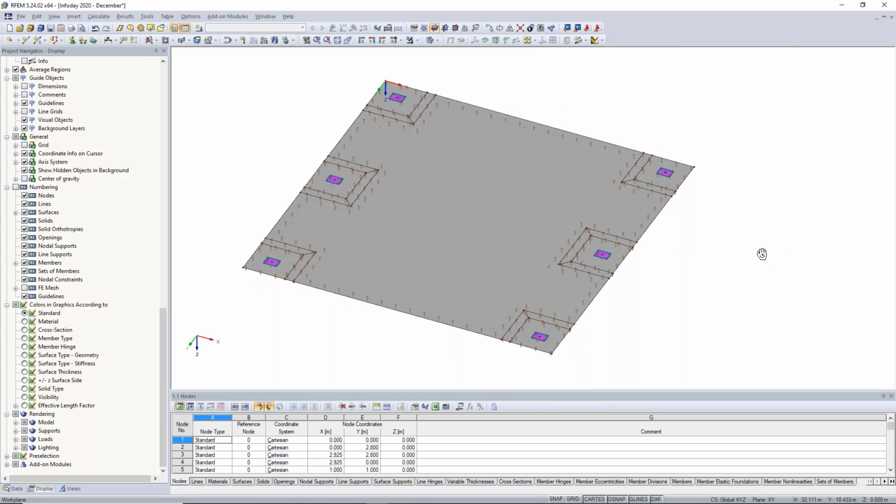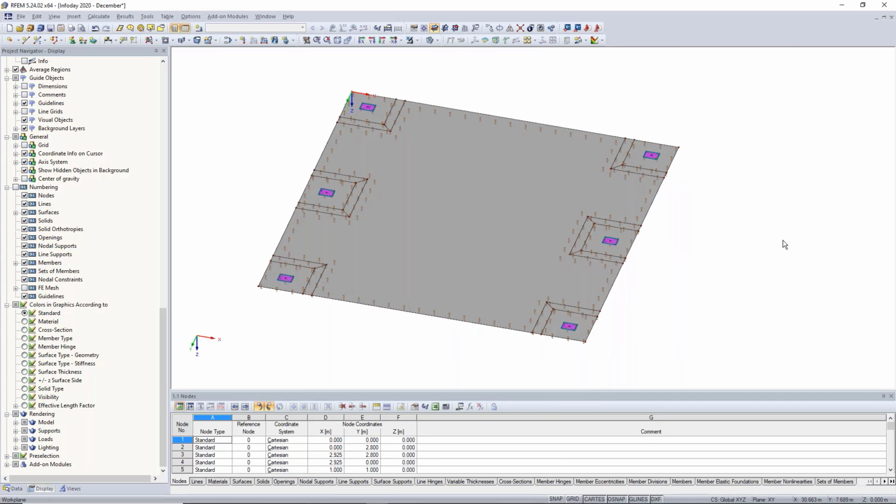And what I have now entered is basically a subgrade reaction modulus method. So basically you just assign a vertical spring on every FE mesh node. The benefit of this is the results are, let's say, okay for practical use. The calculation time is not as big if you use this subgrade reaction modulus method.